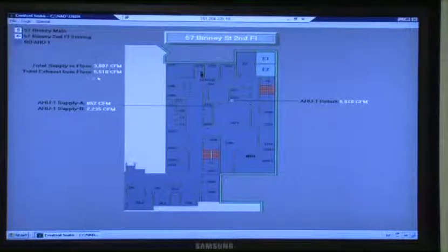And the purge fan, correct, for the MRI. It's not on that screen either, but it's on the other one. That's a good point. The MRI, you were saying the MRI purge exhaust? Purge fan's not on there, but it's on the other screen. Exhaust fan 16. Exhaust fan 16 airflow. Yeah, that's the level 2 MRI, correct?